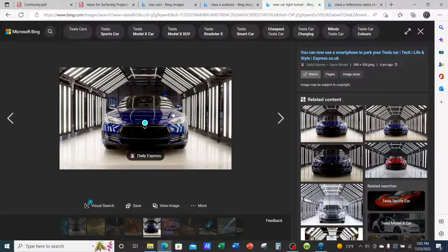So here we have nice, clean reflections, right? As you transition from the hood over to the fender, for example. An area where you don't have a good, clean reflection is in this line here. Notice how the zebra stripe is going up, and then it breaks, and then it continues over here to the left, and then goes upward. So here, by looking at this break, we can tell that we don't have G3 or G2 or G1 continuity.